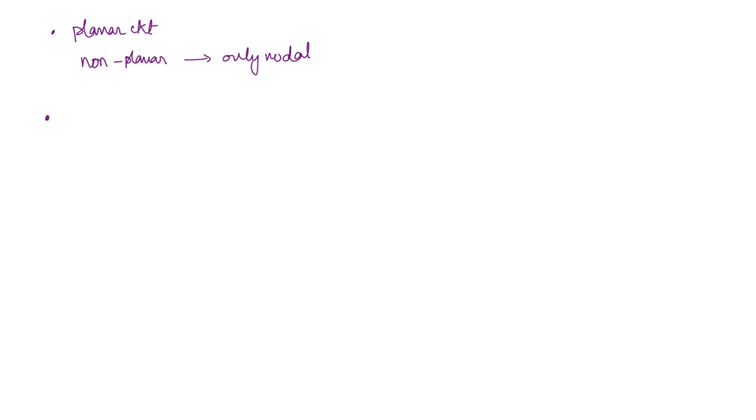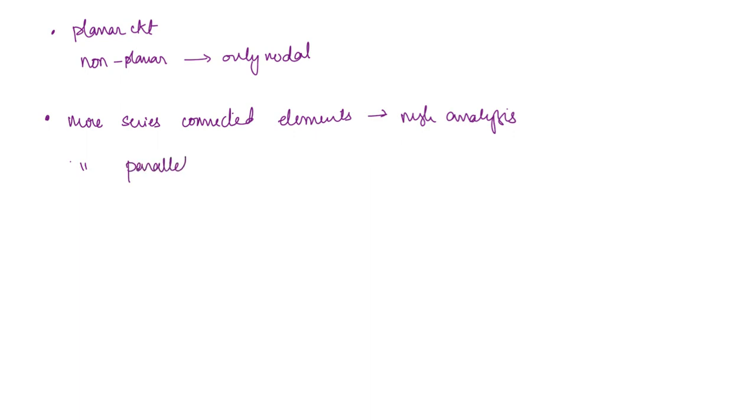If there are more series connected elements, that means more elements are in series, then it is better to do the mesh analysis. And if there are more parallel connected elements, then it is easier to apply the nodal analysis.